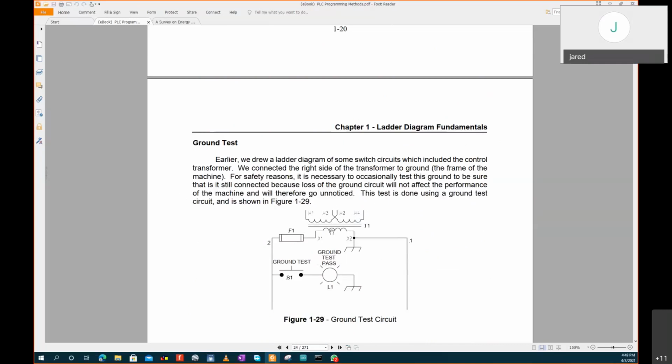You have your transformer here, you have your fuses, your PLC. This is the rung. So we assume this power is going to the PLC to energize the inputs. If you have a short circuit on the transformer, the power will flow this way, and because of the higher current flow, the fuse will blow. Now, when the fuse blows, there is current remaining here. This current will be hanging, but because you ground the system, the current will go into the nearest ground point.